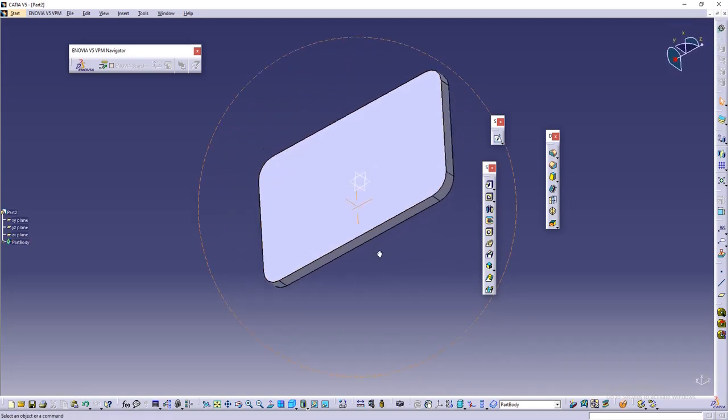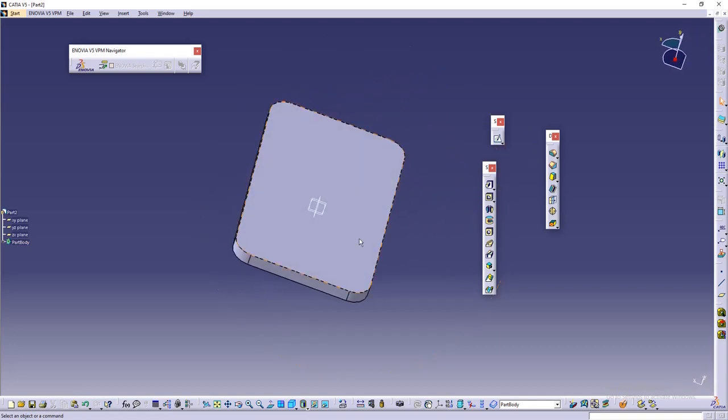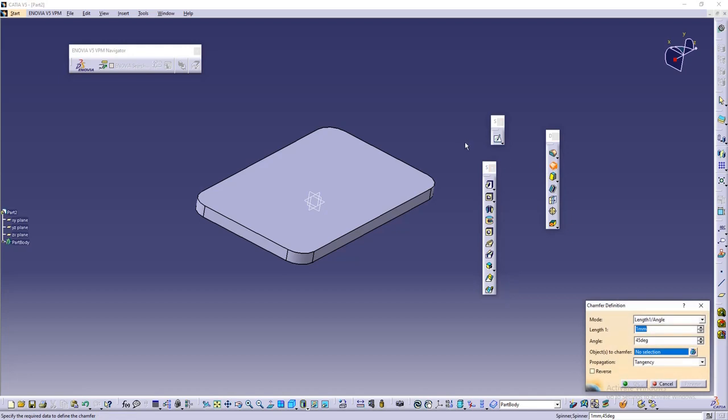What else is there? Maybe some cut or a chamfer on both the sides, so what is the option here? Fillet option, right? So I'll click on the chamfer and then select the edge. So here you can already select the full edge, right?